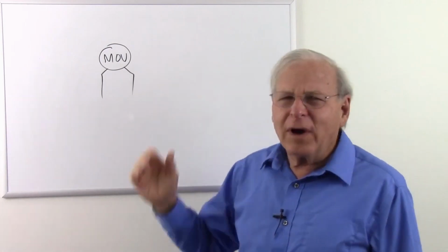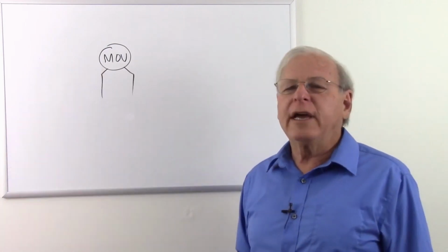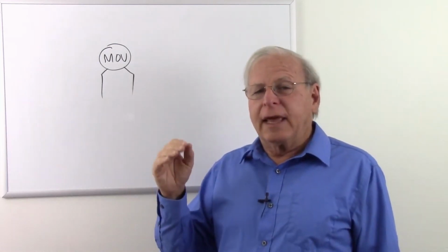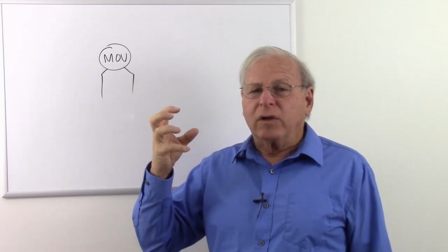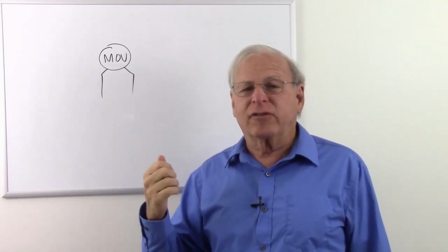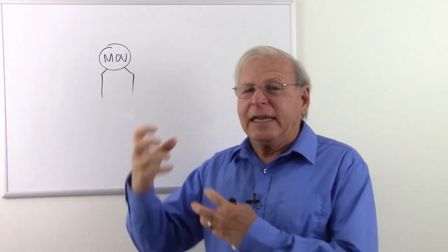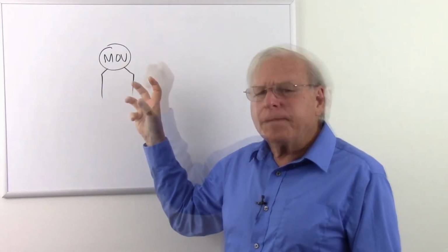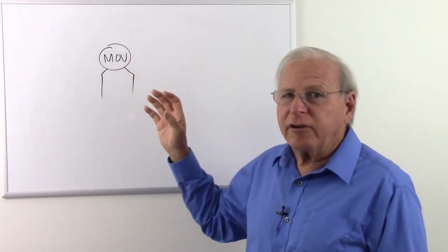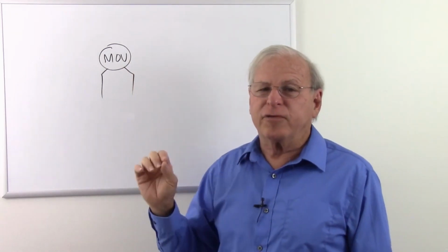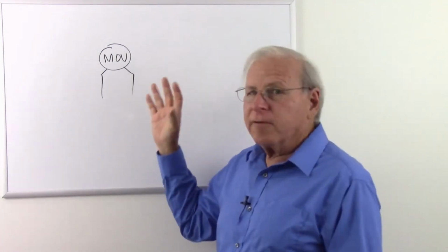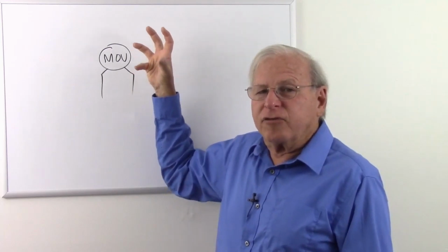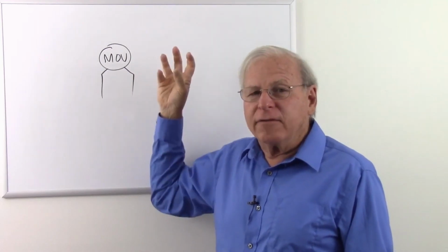They're actually somewhat like a Zener diode. We'll talk about Zener diodes way down the road in solid state devices, but the idea of a Zener diode is that at a certain voltage it will start changing its resistance so that if you try to increase the current, it decreases its resistance so that the voltage stays the same. MOVs are similar, but they're used in a different situation. A Zener diode is used where you need to have a fairly precise voltage under varying currents. An MOV is used where you want to have the resistance drop very low when a high voltage hits it.